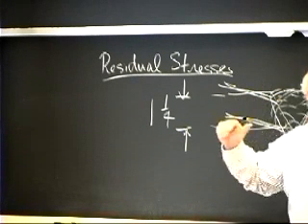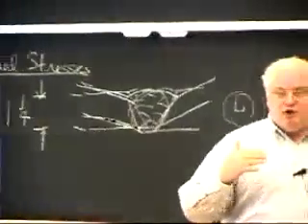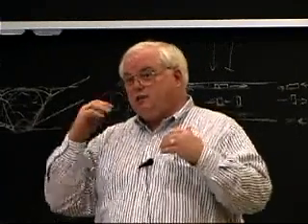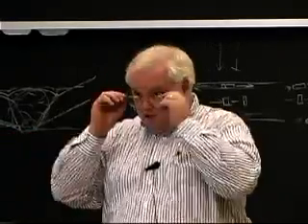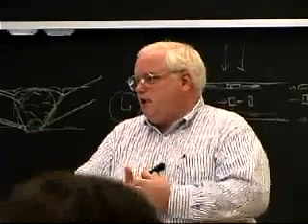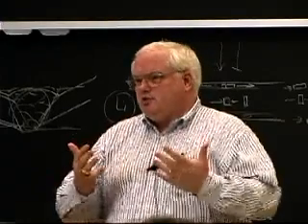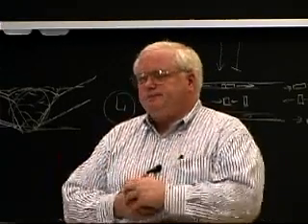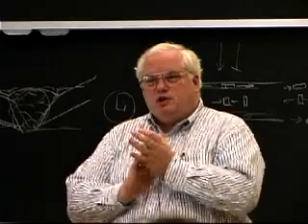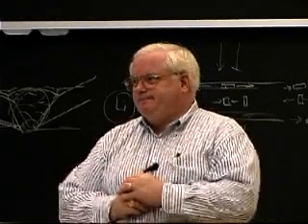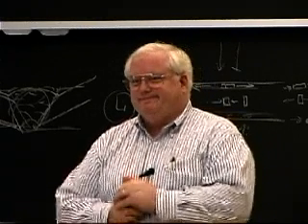Okay? And that means if I put a very slight fatigue load, or a very slight load on something that's already got yield level tensile stresses on the surface, I could get fatigue cracks, right? Even though it's lightly loaded in terms of service stresses, the residual stresses could kill you. So, now I ask all you submariners, why don't we stress relieve the hull of the submarine? Or do we?